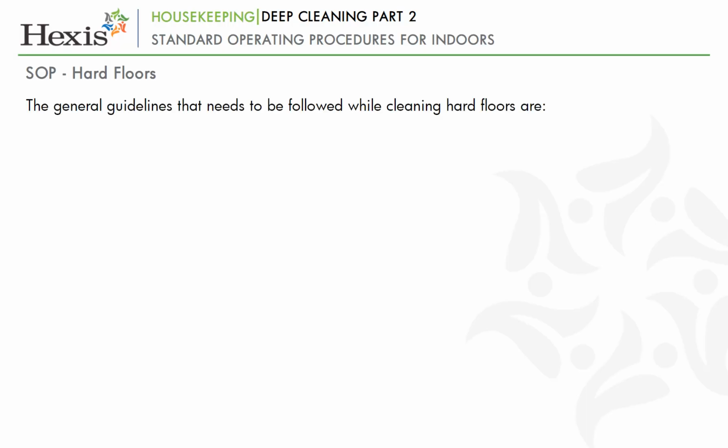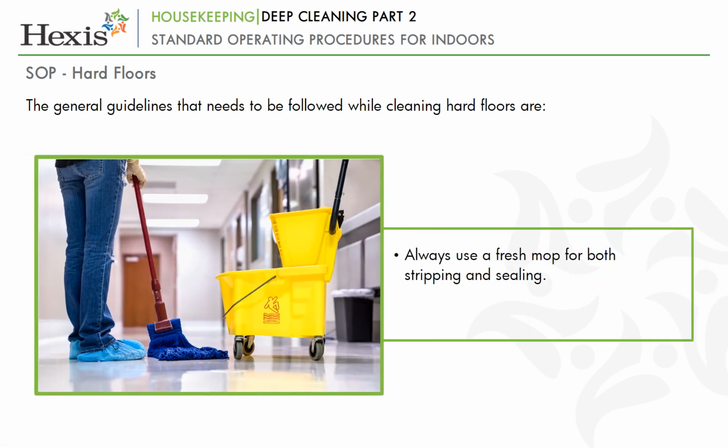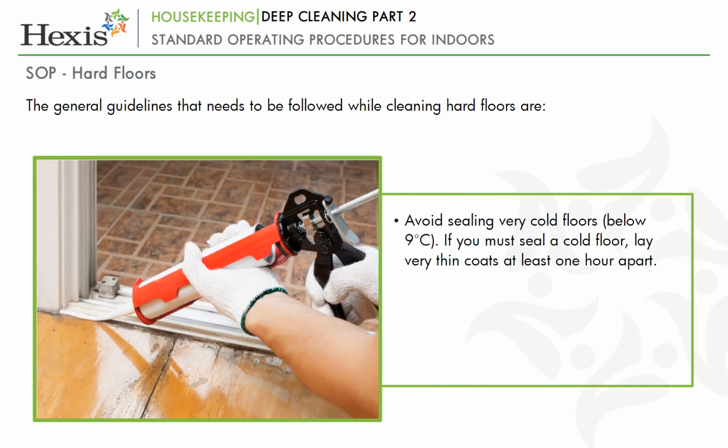The general guidelines that need to be followed while cleaning hard floors are: always use a fresh mop for both stripping and sealing. First, base must be used so the film will bond to the floor and not flake off. Avoid sealing very cold floors, that is below 9 degrees Celsius. If you must seal a cold floor, lay very thin coats at least 1 hour apart.